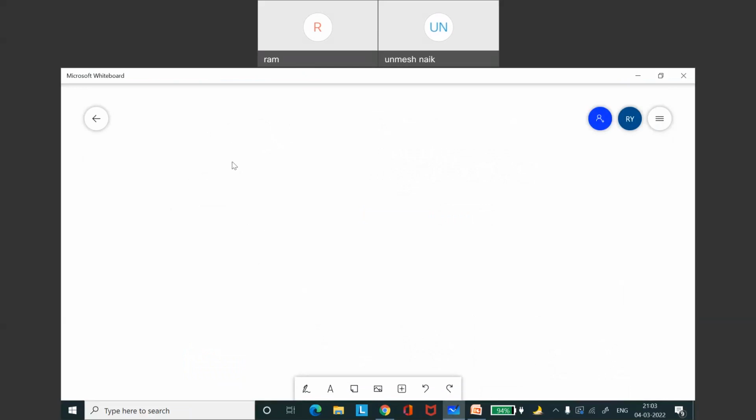Next we talk about armature winding. What is armature winding? Armature winding is nothing but a conductor. Half of the conductor is generally placed under the north pole, and the remaining half is placed under the south pole, because the EMF induced in one part of the winding should aid the other, so that the total EMF will be added. Let me pause.